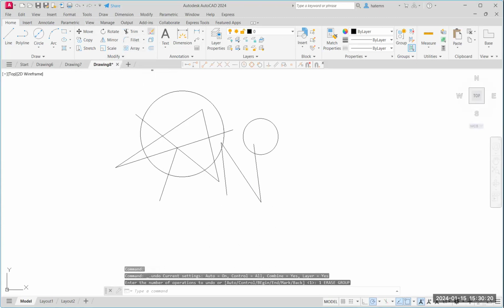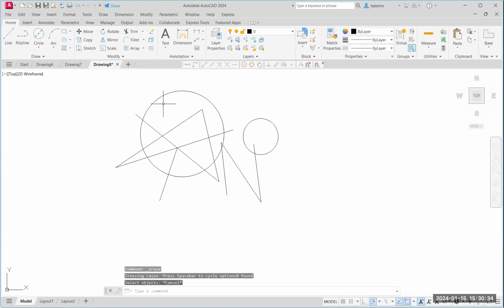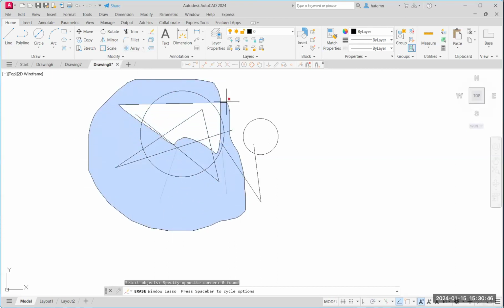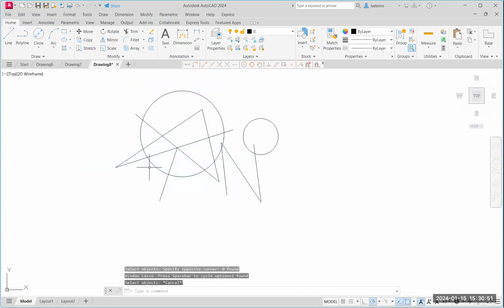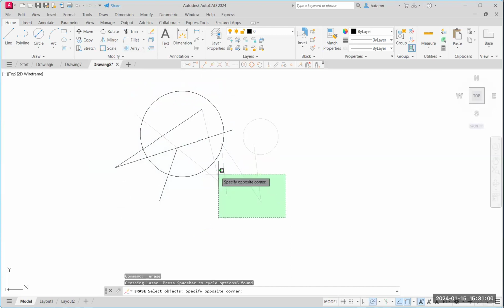Now let's do the hold down option. So if I hold my cursor down, notice whatever I sweep through is going to be erased. So that's where if you hold the mouse button down and you have some items to select, it allows you to select them a little bit easier. The blue is a little bit more difficult, because it has to be completely in that blue area. So see how it's kind of hard if you're holding that button down, but if you're selecting with the green, you can do either. And again, it allows you to select just certain lines without trying to just touch those.